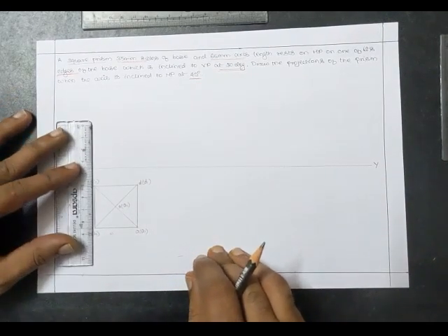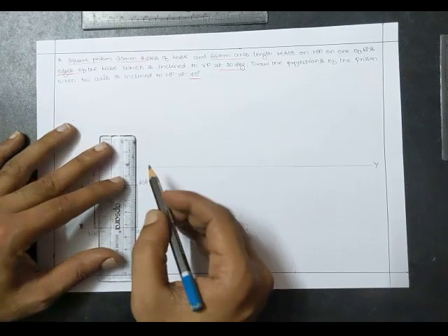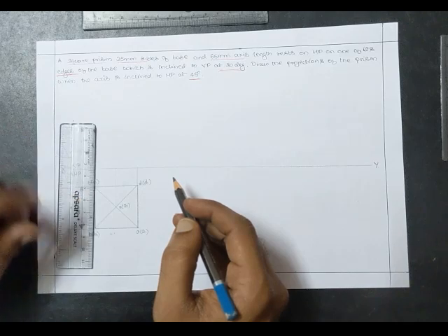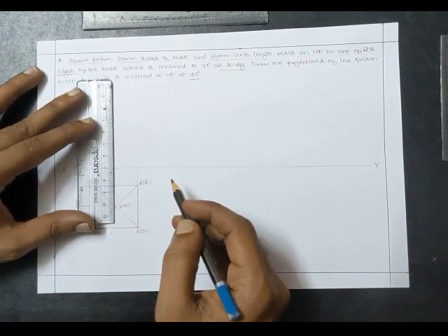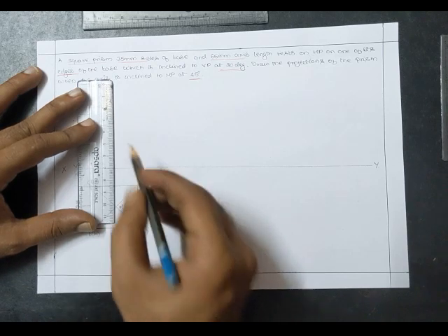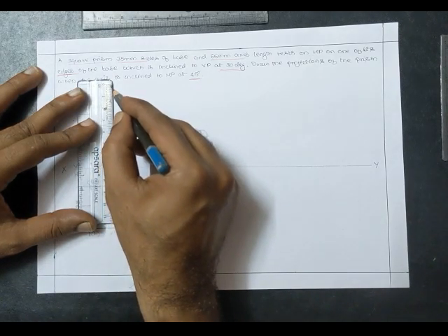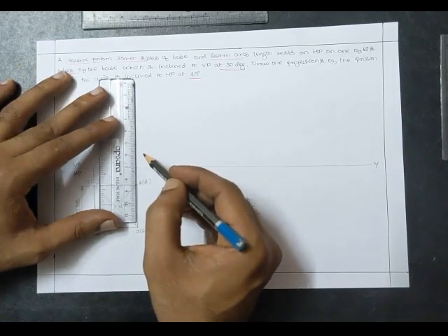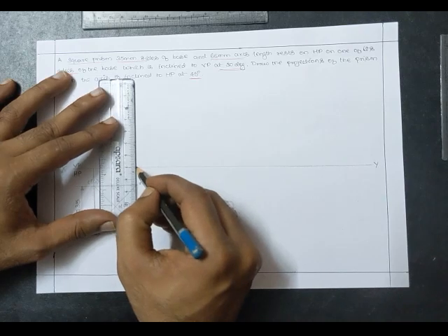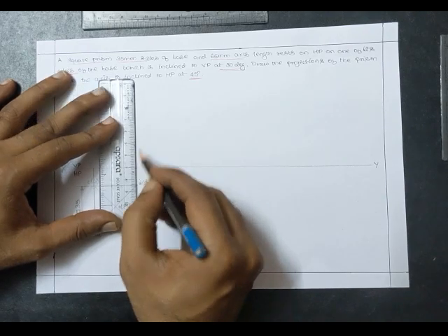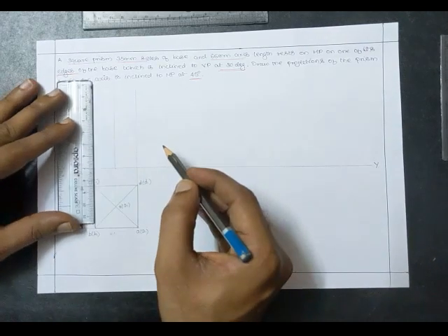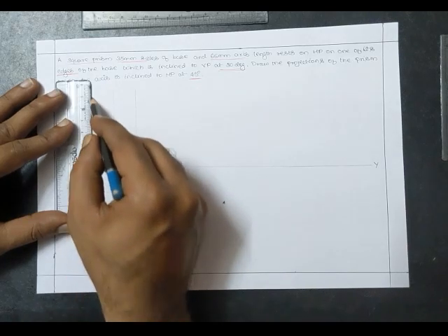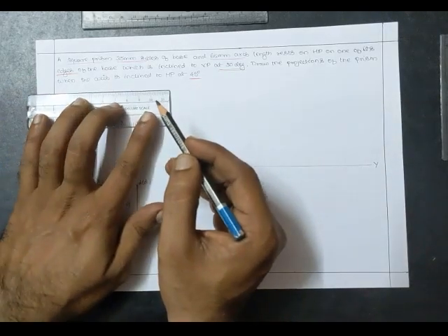Once this is done, you have to draw the projections across the corners to the front view, that is on the XY line. The height given is 65 millimeter, so precisely draw the height. The axis is visible. You should be very careful because a slight deviation in the constructions may lead to errors in the later stages. As much as possible, try to avoid mistakes.